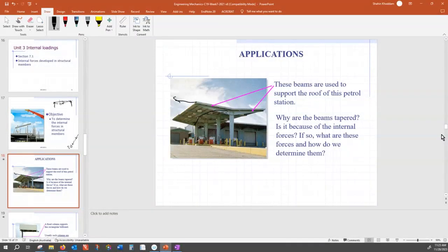Anyone can visualize that. Okay? So, with that simple visualization, you answered a very fundamental question. The fundamental question is: is that structure a bar or a beam? It is a beam. Why? Because the radius of curvature changes. Okay? Now, the next question.